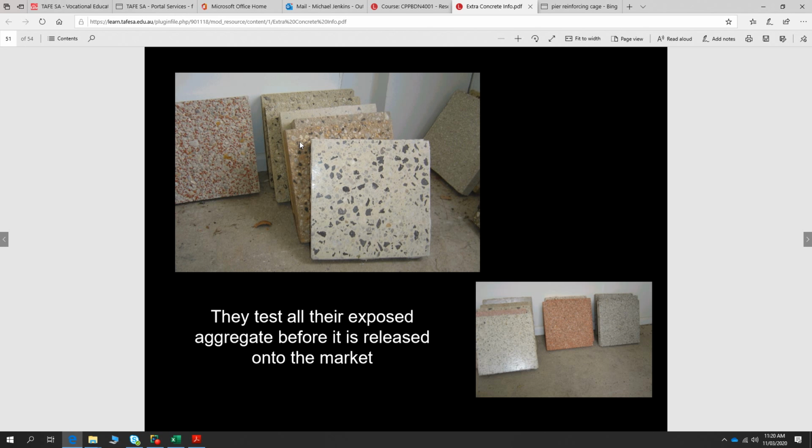Another thing, have you done sprinkling salt on concrete? Yeah, rock salt. So that's another way of getting grip into concrete: you sprinkle rock salt onto the top of it after it's finished. And then once it's all hardened and cured properly, you wash that away as well, and the salt obviously washes away and creates little cavities in there. I can't remember what the finish is called, but basically you sprinkle rock salt on there.